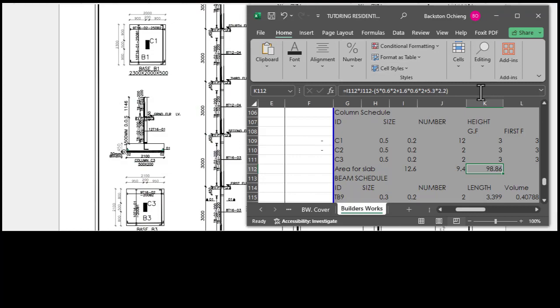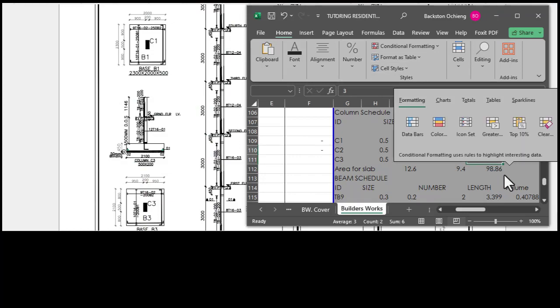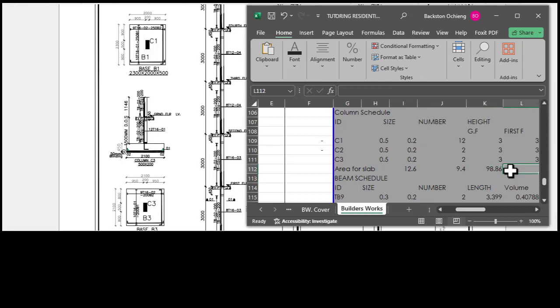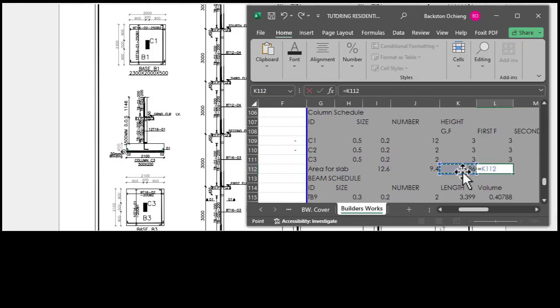Okay, so once we've counted that, so these should be multiplied by, this is equals to the 98, and then we multiply by 4. Okay, so of course you can decide to assort your slabs in terms of just measuring them on every floor, but for these types of the summarized bill of quantity that we are doing, we are adding them all together. So for the 4 floors, we assort them together, and then now there is another slab.